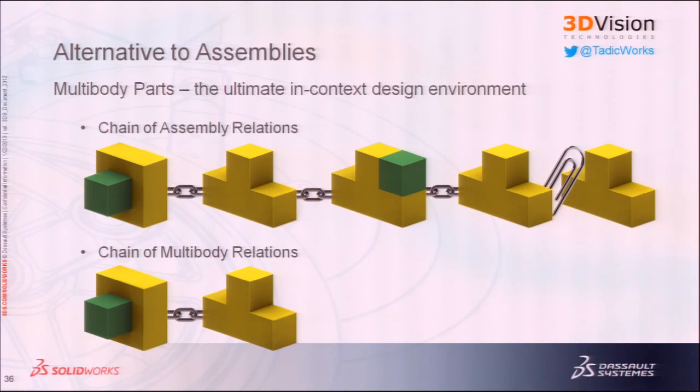You've got the in-place mate. You're creating a feature that's inserted into a part that's relying on the assembly file, that's dependent on all these other parts around it, offset from it or dimensioned to it, coincident to it, and then all those parts are dependent on the mates that are locating them all, and they may or may not be dynamic.